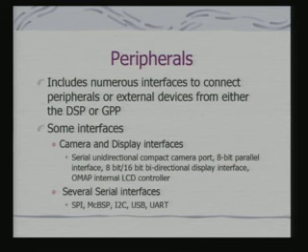It provides camera and display interfaces, because if I am targeting these kinds of embedded portable terminals, then they will typically have a camera connected to them, and so that camera interface forms an integral component of this SoC. It has basically 2 camera interfaces, a serial unidirectional one called the compact camera port, as well as an 8-bit parallel interface.